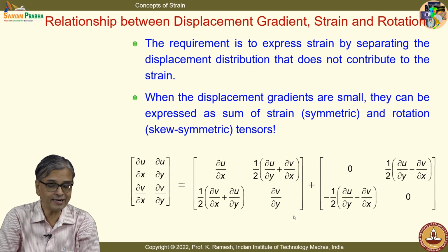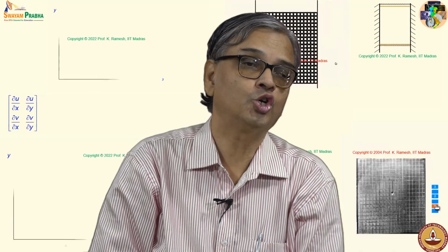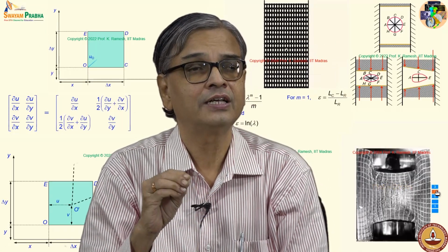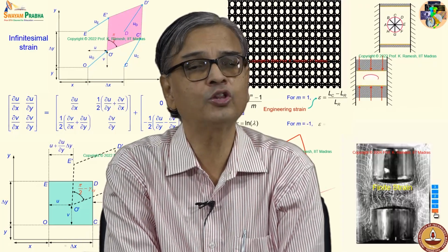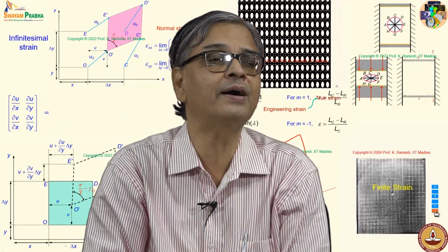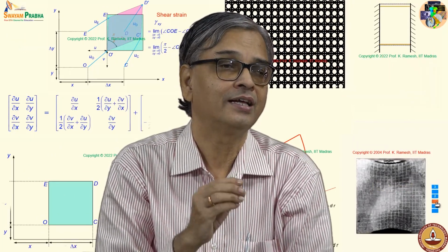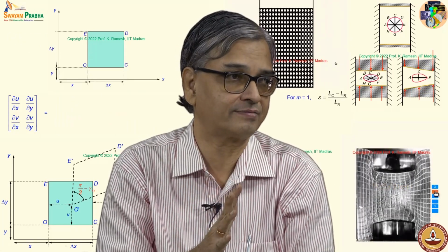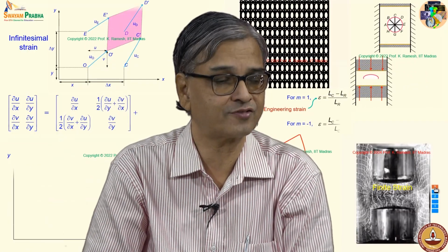So, this quantity transforms like a tensor, and you call that a strain tensor. You should know the distinction from the engineering definition of shear strain. Gamma xy is used repeatedly; both symbols are used. When it is used as gamma xy, only one half of gamma xy is to be taken as a component in the strain tensor. Only this obeys the laws of tensorial transformation.